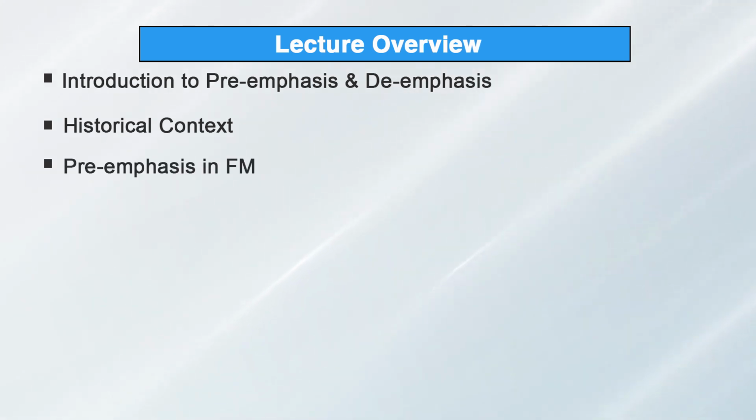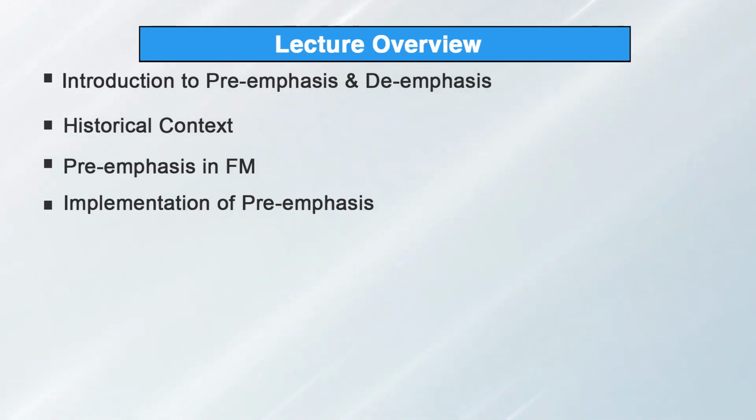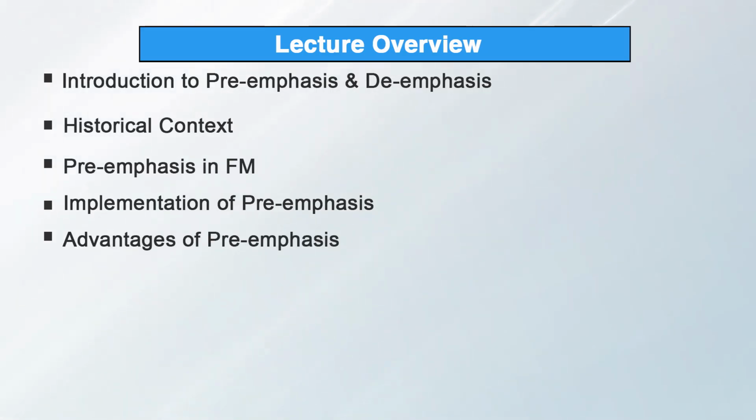Pre-emphasis, our next topic, involves boosting the higher frequency components of the audio signal before modulation. Moving on to its implementation, pre-emphasis employs a high pass filter with a specific frequency response curve. The advantages of pre-emphasis will be discussed. Then we will talk about the applications of pre-emphasis.